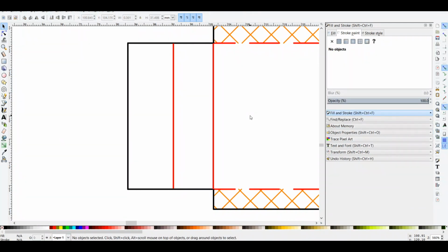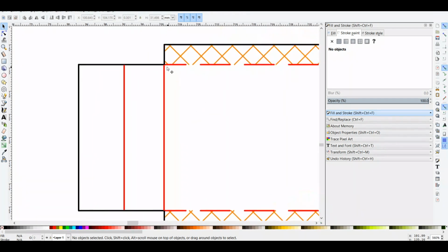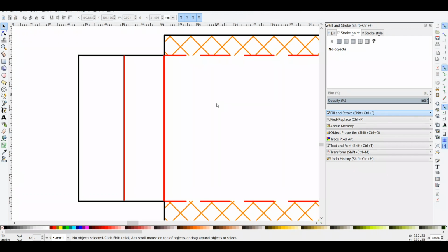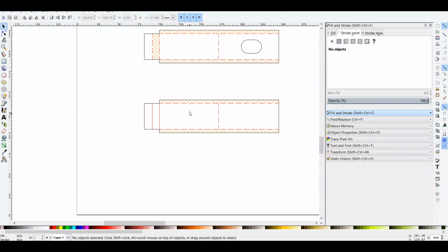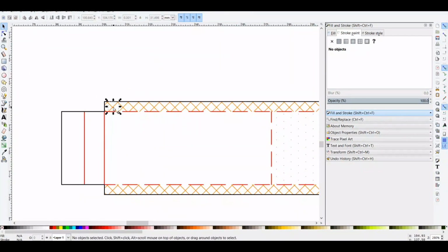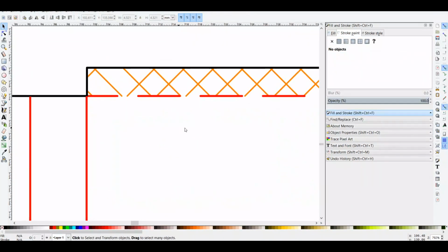So when the G code generator is generating G code, it will generate G code to tell the machine to go from this point straight down to the point on the other side, instead of going straight and then going up, then going there, coming down again and cutting again, going up, coming down, cutting again, which wastes a lot of time, and then you don't get a straight fine cut. So we are going to repeat the same procedure on all of these. I'm going to do it quickly.